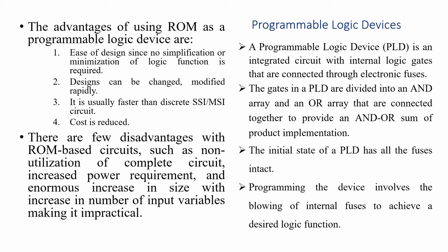There are a few disadvantages with ROM based circuits, such as non-utilization of the complete circuit, increased power requirement, and an enormous increase in size with an increase in the number of input variables, making it impractical. These are the disadvantages of ROM based designs. Now let us see other PLD devices.